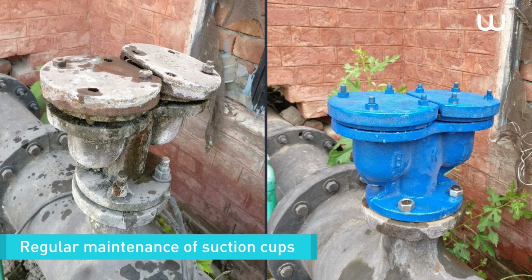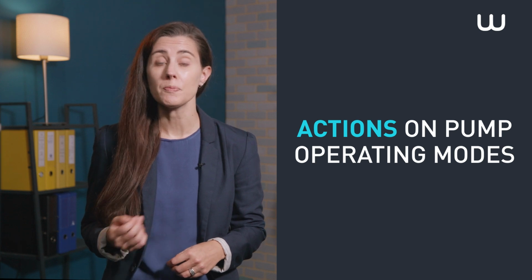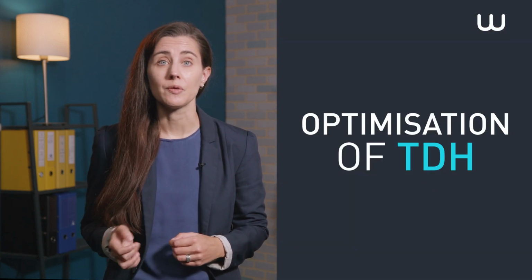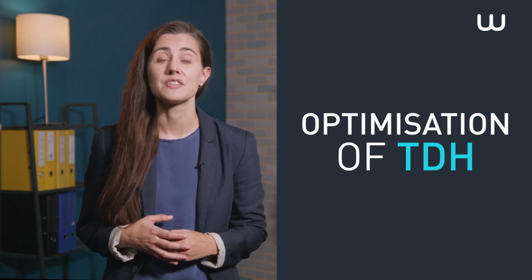Actions on pump operating modes can also permit energy consumption to be optimized, namely through the parallel use of pumps, which must be planned according to the flow to be pumped during the day. Regulation, thanks to variable frequency drives with fixed or variable set points, depending on operating constraints. The optimization of TDH, thanks to drawdown at the level of suction on an upper section of the storage tank and filling by the base of the tank at discharge. This optimization can impact water quality.